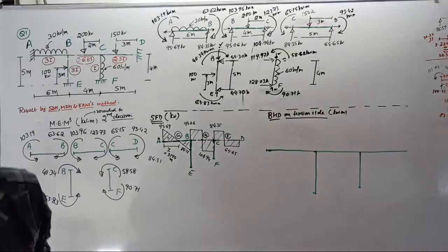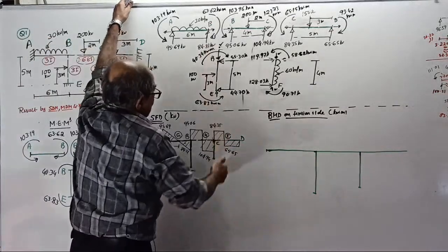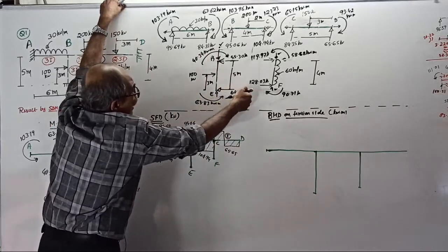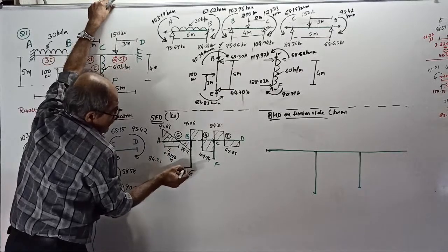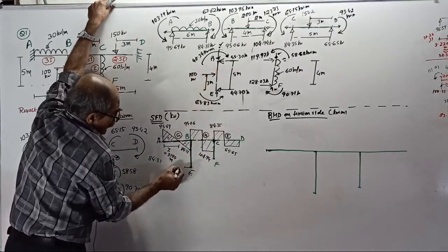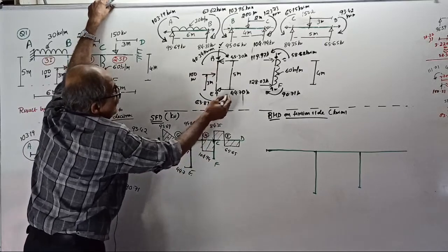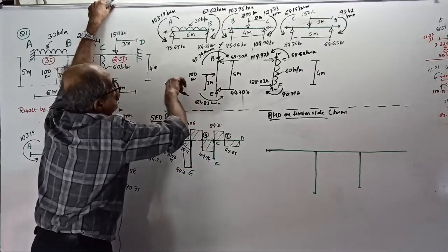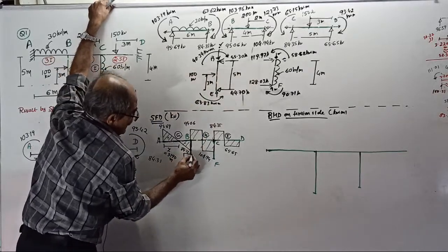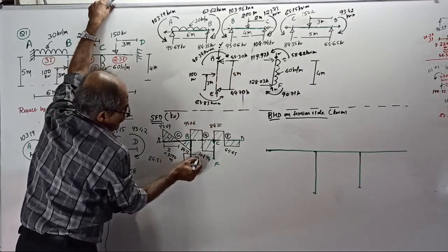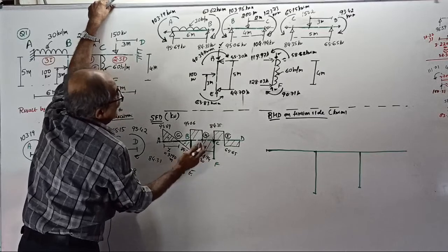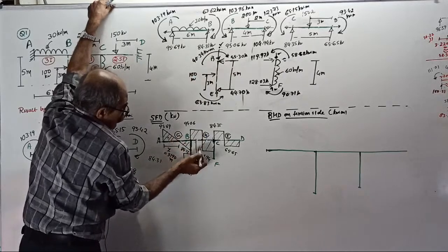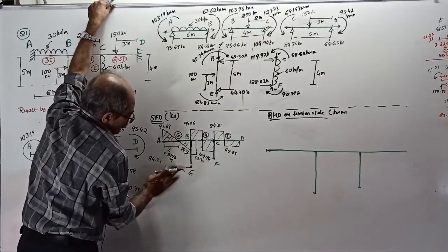Okay. Now, vertical member. Vertical member, shear force is this way. You do one thing, start from here. See, start from here. Go left by 44.7. I will take bottom this way, 44.7. Then, no load up to here. Up to where? Up to 3 meter. Somewhere here, no load. Go right by 100. Right by 100. That value will be 53.3. Then again go up and no load. Lastly, come back by 53.3. Oh, out of scale. I should reduce this one, 44.7.